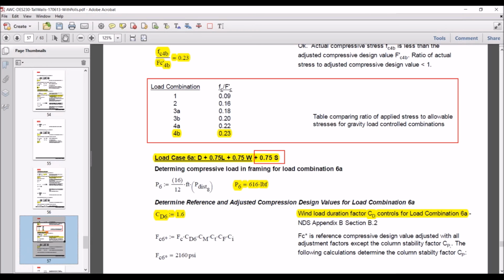The Canadian Wood Council develops WoodWorks software, so if you develop your loads from ASCE 7, your C&C loads, your main wind force loads, and your gravity loads, you could design your studs using the WoodWorks software or other software as well that would design a stud. But these CAD sheets, for example, aren't available out there to the general public just because of liability reasons.